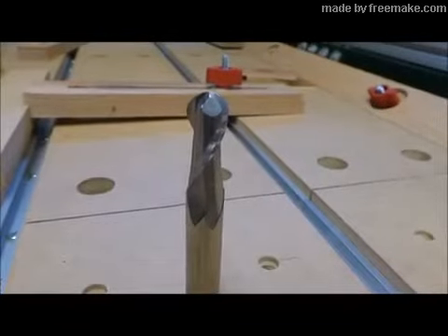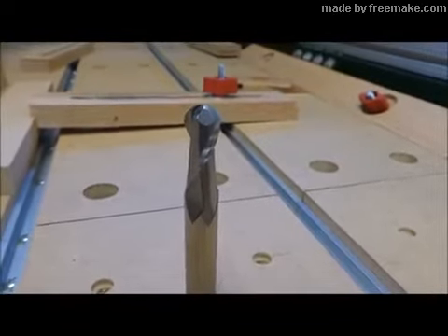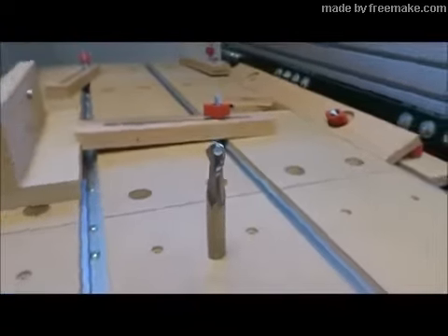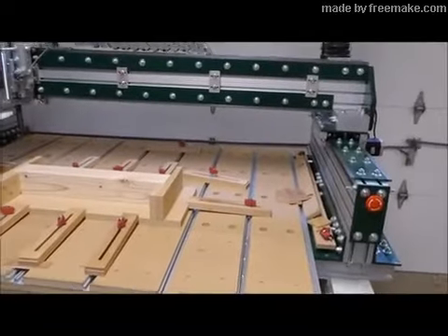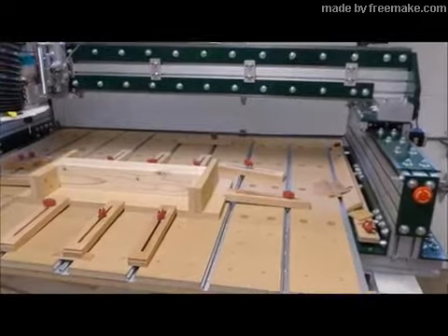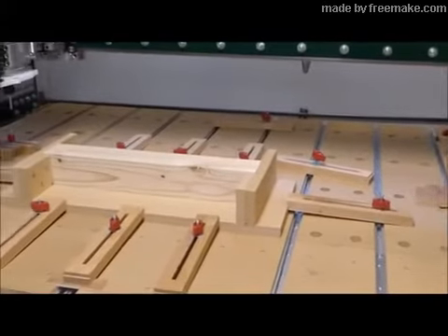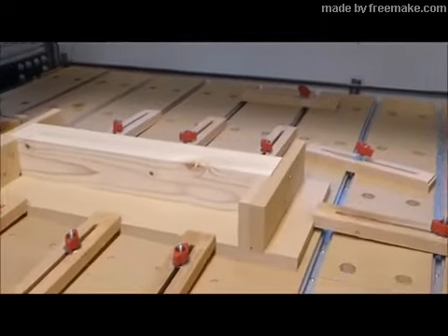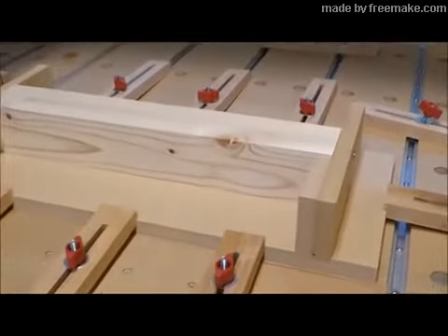This is the router bit used for the machining of both roughing and finishing passes. It is a solid carbide 1/2 inch ball end mill from Precision Tool Company. Here is the spruce stock held in a jig. The jig is made from MDF, which is clamped to the CNC table. The stock is securely held with 2 screws through the jig's uprights on each end.